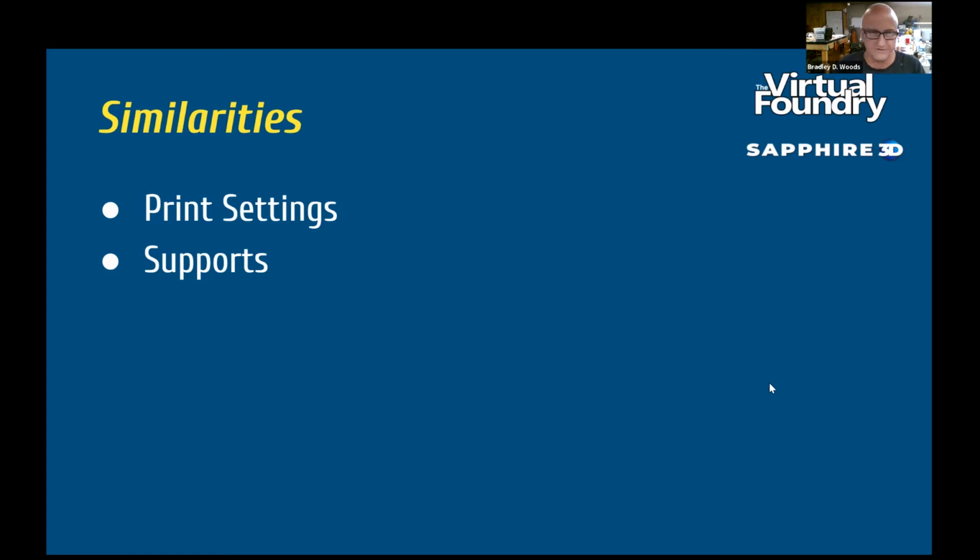What happens is our material is very viscous. So compared to pushing PLA through the print nozzle, it's a lot more like pushing bread dough through the nozzle. So we have people turn the flow rate up to about 140%, somewhere in there. Start with 135. You may need to go higher. You may need to go lower. It can vary a little bit by printers, but that's the easiest place to start. So my main point is the settings to print Filamet are not particularly unique.